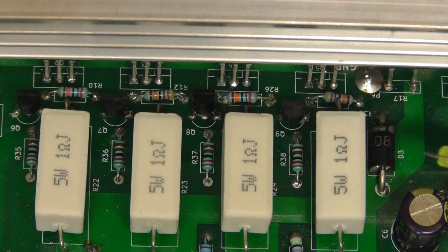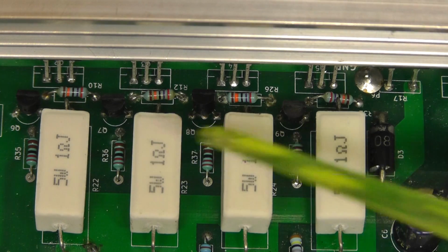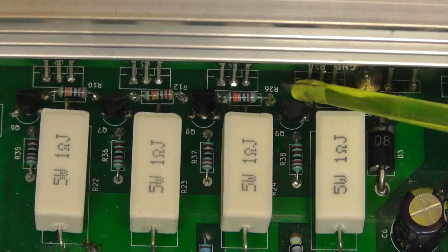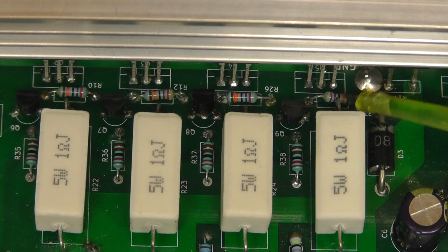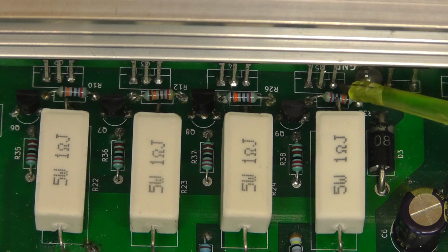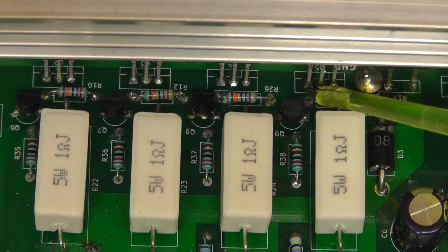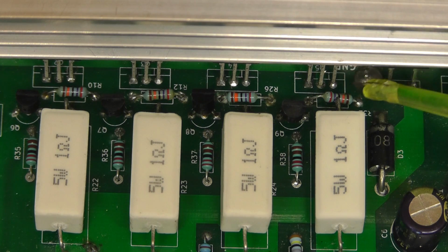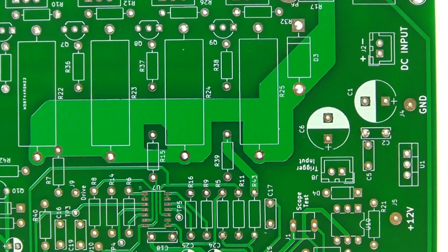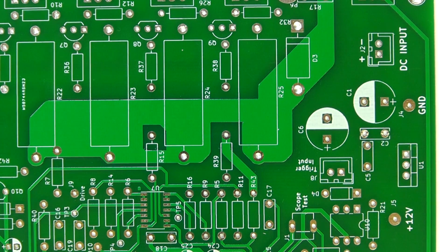Right, here we have the closer view of that area with the power resistors, and just behind there you'll see those 4 resistors, which are in the emitter return of the PN2222A transistors. Those 4 resistors have now been changed from a 47k resistor to a 270k resistor. Right, well, the next thing we're going to do is fix that little issue we have